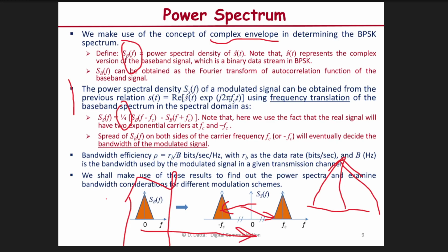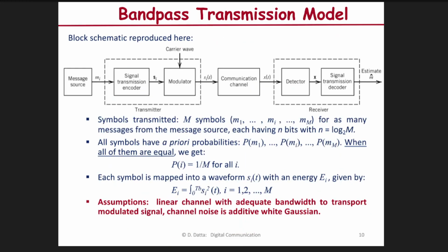Okay. So if I know the SBF, I can write the complete spectrum of the modulated signal by multiplying 1/4 with SBF minus FC and SBF plus FC.